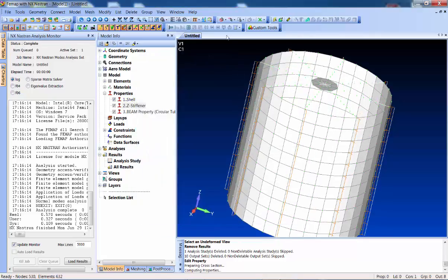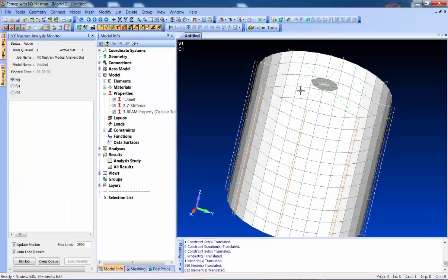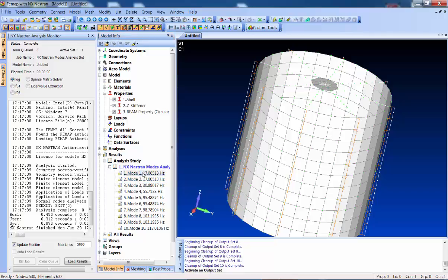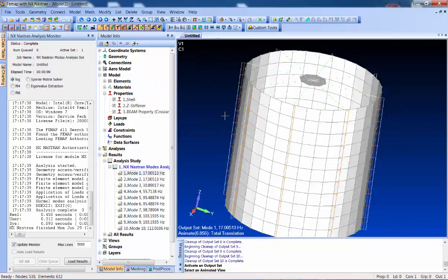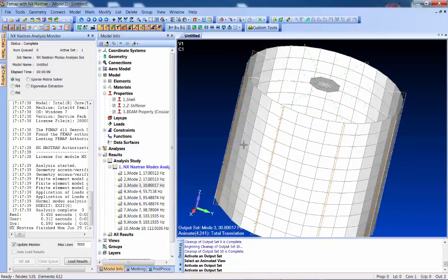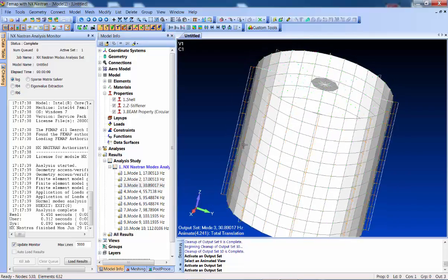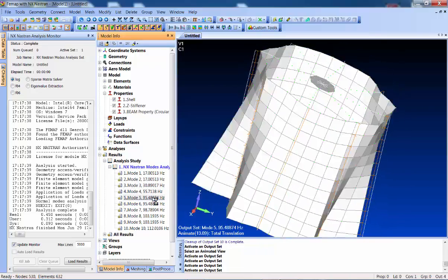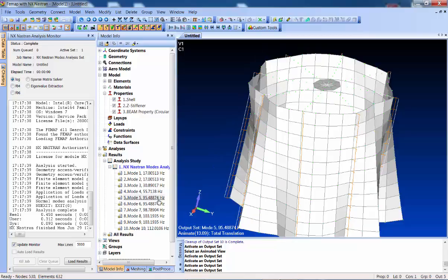You'll see that he gets taller out there. So let's just reanalyze. And we'll stiffen that guy up a little bit. So we go back to the results. You'll see the modes changed a little bit. Not a lot though. I guess that didn't really change that mode a whole bunch. They're certainly different. But that's kind of the manual meshing, mesh editing, copying, rotating things you can do with Femap and Femap with NX Nastran.